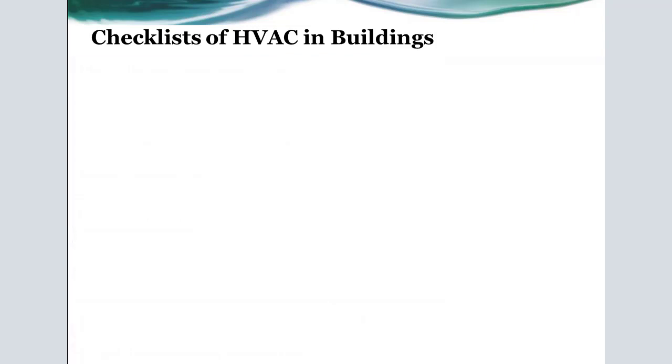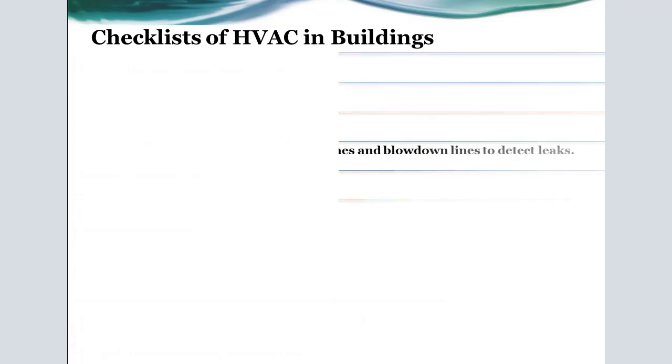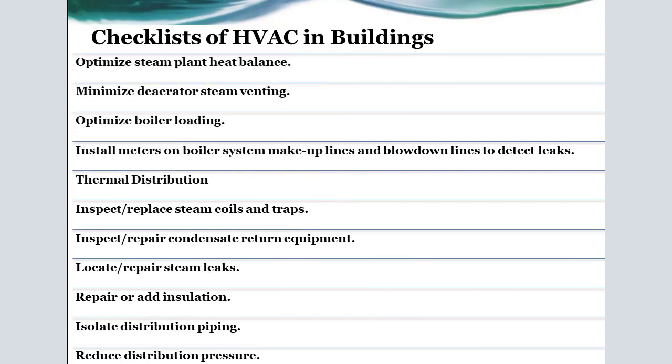This checklist also includes another issue: optimizing steam plant heat balance, minimizing deaerator steam venting, and optimizing the boiler loading.